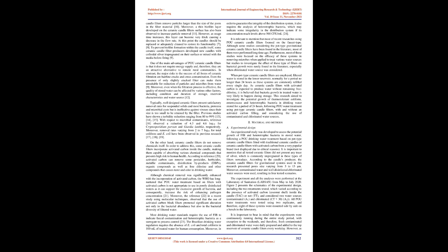Previous studies have shown a turbidity reduction ranging from 80 to 99%. 13, 14, 15. With respect to microbial contaminants, reference 16 observed a reduction of 4.3 and 4.6 log10 for Cryptosporidium parvum and Giardia lamblia, respectively. Moreover, removal rates varying from 2 to 7 log10 for total coliform and E. coli have been observed in previous research.